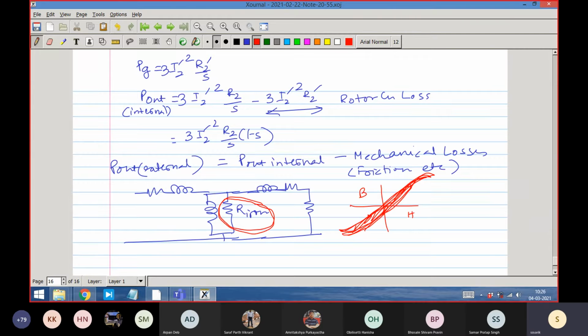So there will be a stator iron loss, because the moment there is a change in the magnetic field polarity in any magnet, there will be iron loss, because the magnetic field is always changing. Positive, negative, they have to change according to the flux density, but they don't go through the same path, and therefore there is a loss trapped in the iron part. So we conclude that the stator has iron loss.